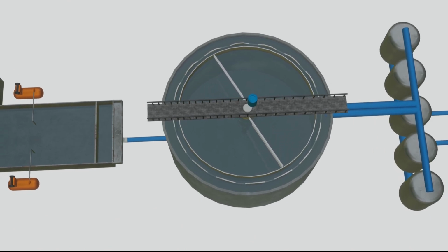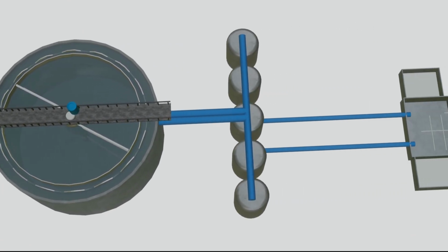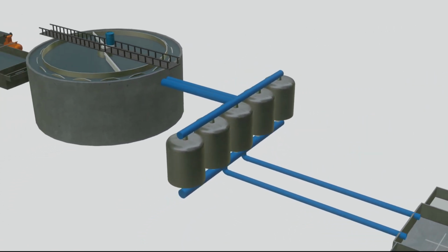This is the key to making the microorganisms keep working to separate sludge from water. It will result in water at the top of the tank and sludge accumulated at the bottom of the tank. This tank has a scrapper too, so that sludge can be removed continuously as the scrapper rotates. After the secondary clarifier, wastewater flows to the output channel and comes into the filtration chamber.